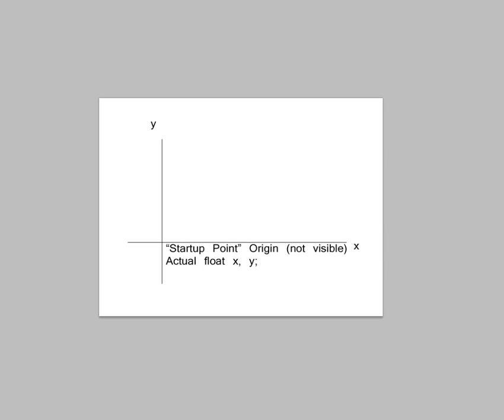First, you can't actually see the startup point in Revit. There are no 0,0 crosshairs and no icon dedicated to the task. Instead, the only way to locate the internal origin is to unclip the project base point, right-click on it, and click the Move to Startup Location option. It's not a particularly important origin, as it turns out, except in 2 respects.